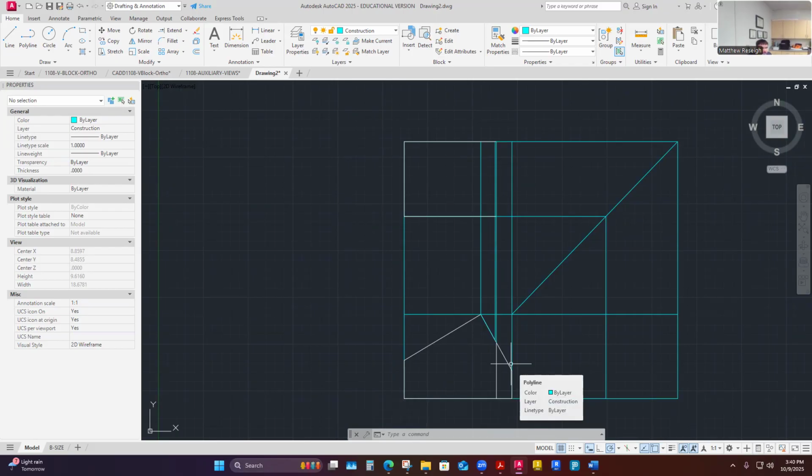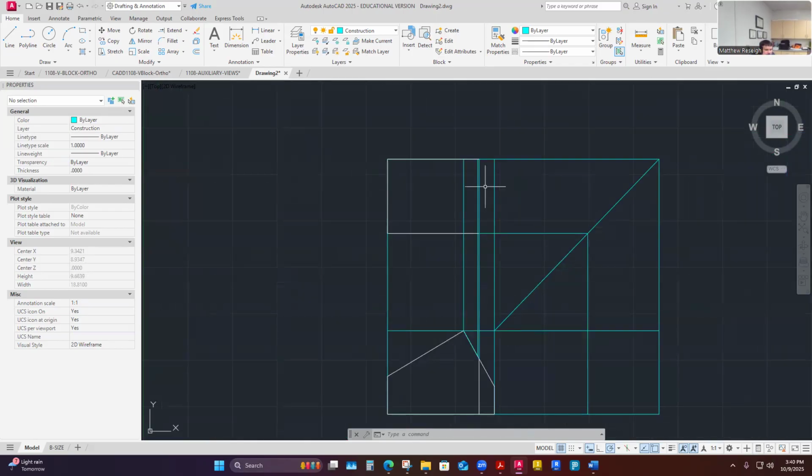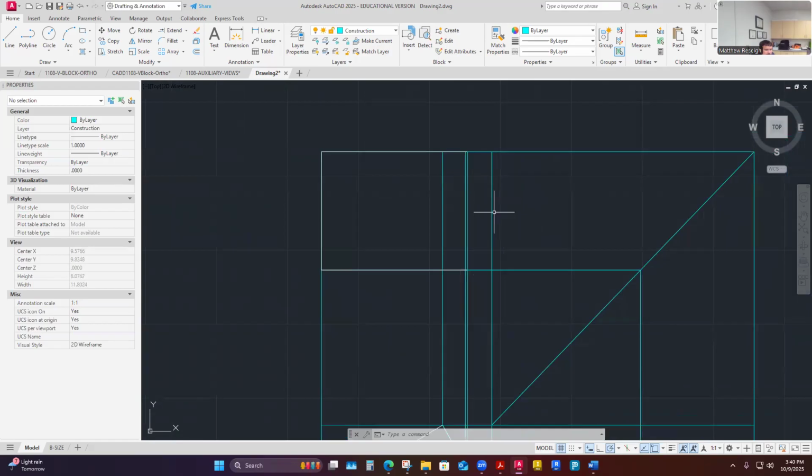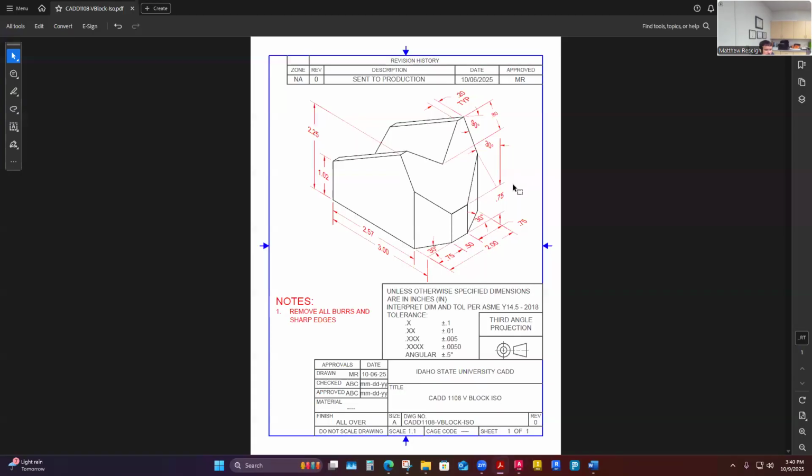So okay. I like this though. Where I'm stopping there is I'm starting to look at, okay, I'm looking down. I've kind of drawn in that to that point. From that point is this point is where I've drawn all the way over to that 257. From that point to the right side view, it miters over there. In the top view, I should see this 30-degree miter essentially.